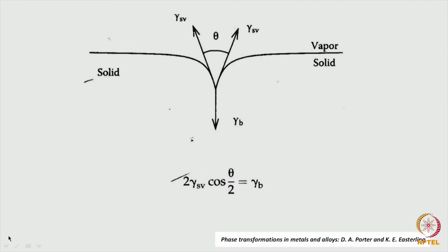But generally, computational calculation of grain boundary energy has lots of difficulties, because there is a discontinuity at the boundary. Atoms are not at equilibrium position across the boundary, because the separation between the atoms doesn't correspond to equilibrium separation, but could be values different from that.